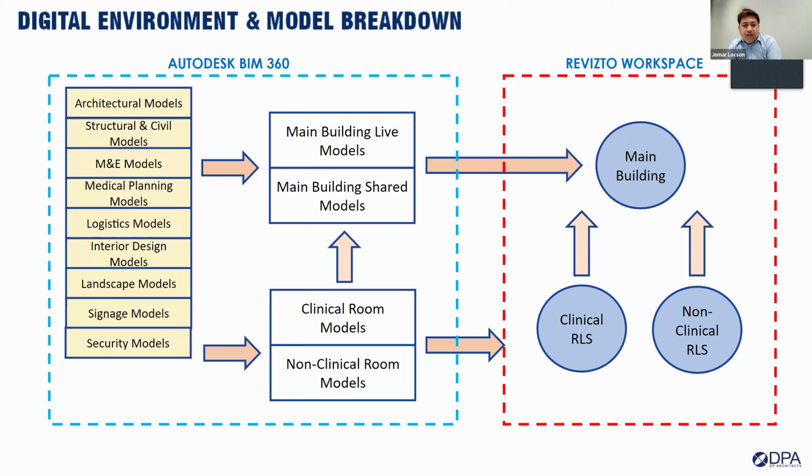The link models are also separated into 2 groups: clinical room models and non-clinical room models. Towards the design review process, we will create a Revizto workspace that separates clinical and non-clinical RLS, or room layout sheets, as we call them. And they will then be populated into the main building for the necessary coordination.